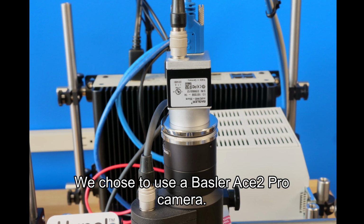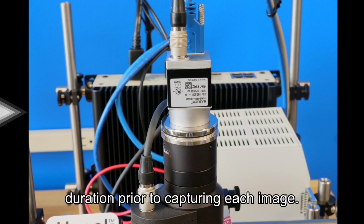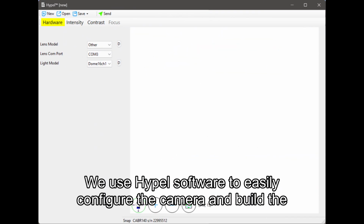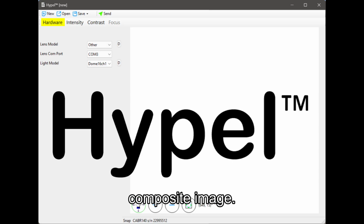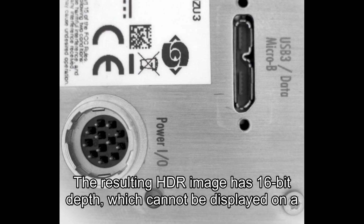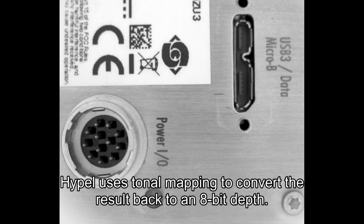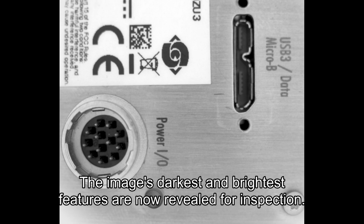We chose to use a Basler ace 2 Pro camera. It has a sequencing function that can automatically change the exposure duration prior to capturing each image. We use Hypal software to easily configure the camera and build the composite image. We could have instead used Zebra Aurora Design Assistant software, but it would have taken us longer to create a flowchart. The resulting HDR image has 16-bit depth, which cannot be displayed on a computer monitor. Hypal uses tone mapping to convert the result back to an 8-bit depth. The image's darkest and brightest features are now revealed for inspection.